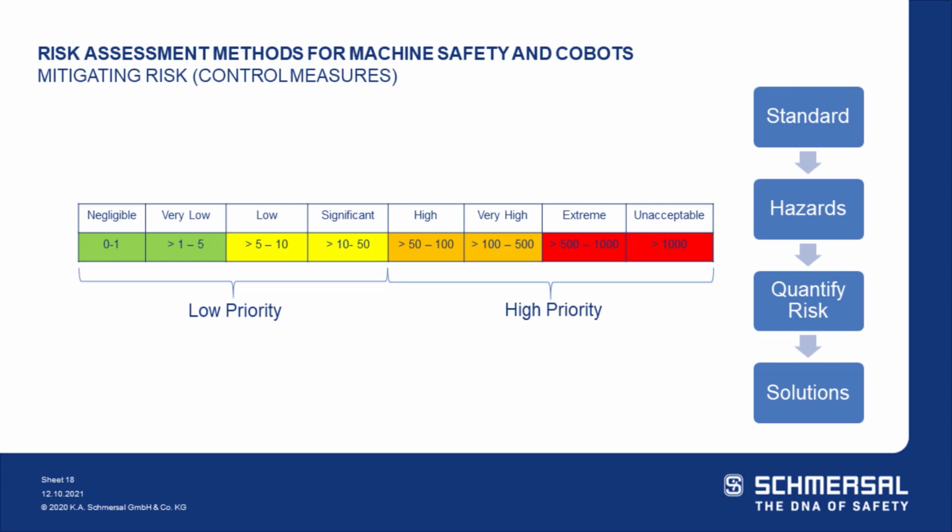And when it's subjective, I'm hoping that we pick something close enough that if my very high and your high differ, it doesn't matter, because now it's in the high priority. It's going to get fixed just as fast as a very high or an extreme. So we're hoping for that range. And machine builders, here you have a very good chance to design out or add certain features, or talk with the company you're building the machine for and say, hey, we have an unacceptable hazard here. Maybe we want to talk about something different to prevent the possible hazard or injuries.